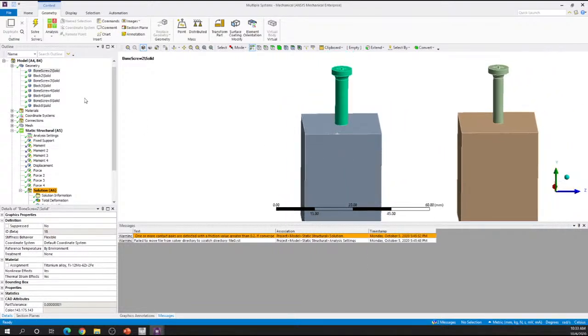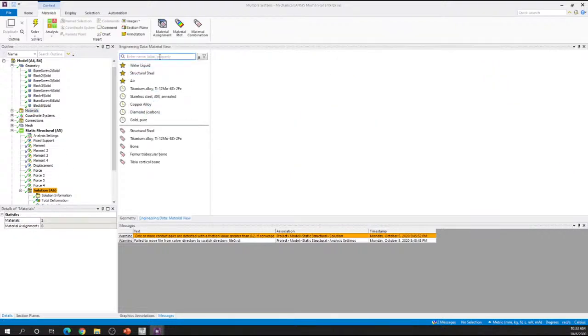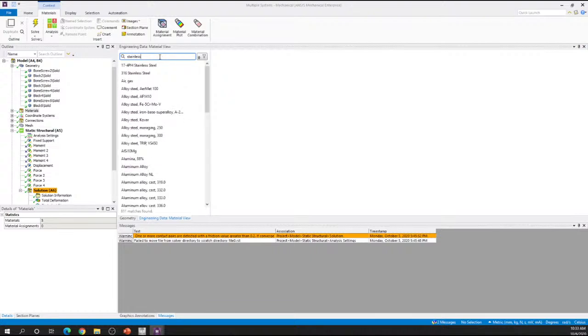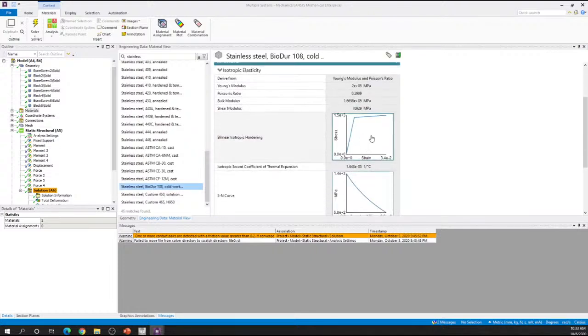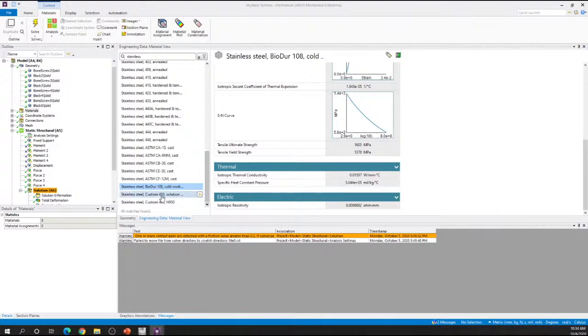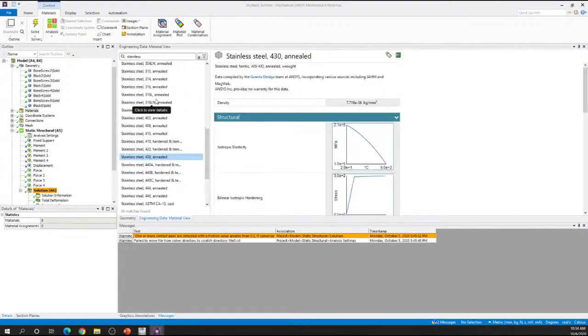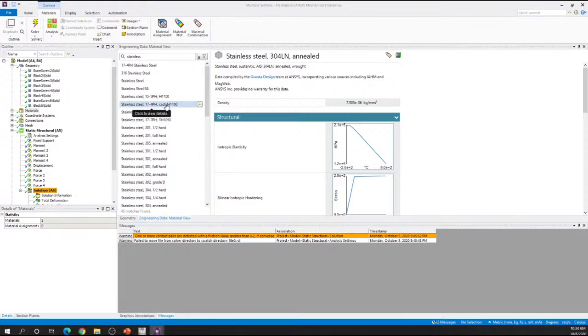So the first thing is that ANSYS has a wide range of material properties. If we go to the materials section, we can look at different types of, let's do stainless steel. And you can see we have a huge range of stainless steel materials already available. These materials have their fatigue curves. So these are estimated fatigue curves. If you're using a specific material, you should always double check these values and make sure they make sense. But these are fatigue curves as well as plasticity models, thermal models, electrical resistivity models. If we're using stainless steel, you can see we have a great set of materials.